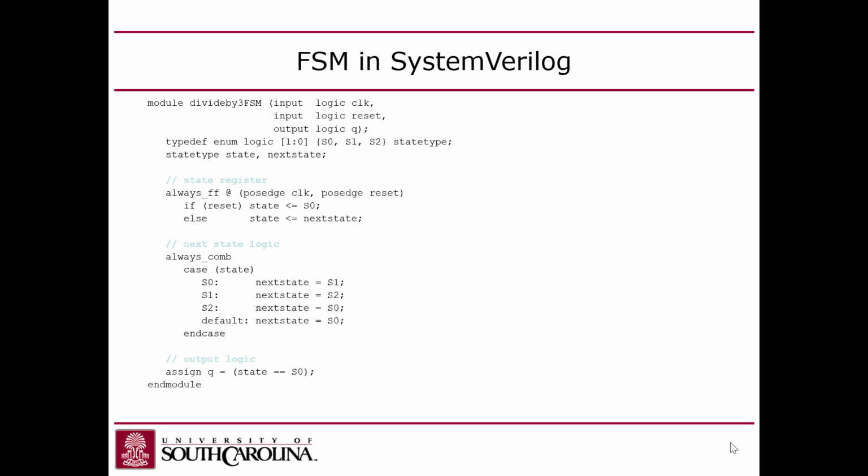20. Okay, so how do you build state machines in Verilog? So far we've looked at how to do it in the 211 style, when you actually have to build them out of gates and primitives. In Verilog, you design the finite state machines in a way that matches up to the way you do it with logic gates. You have a next state logic section, which is its own always block. You have an output logic, which can be an assign or an always block.